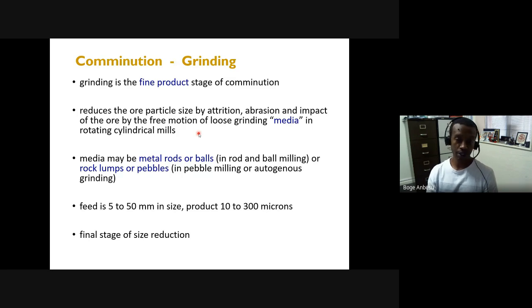So as I said, always, a grinding flow sheet is designed around the idea of being able to produce liberated particles. And that will obviously be dictated by how fine or how coarse the particles are. So your mill, your grinding stage, should be able to achieve those particle sizes. As I said, grinding, especially the ball mill stage, works well until about 75, 80 microns.